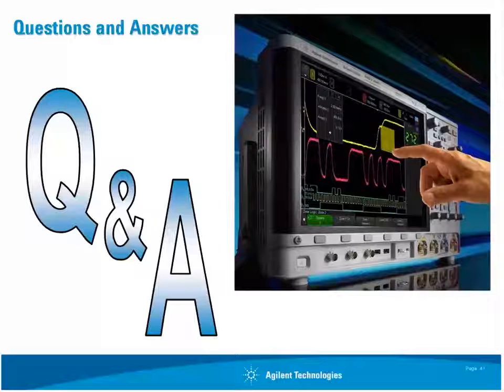What the fast waveform update rate is doing is actually capturing more noise. Noise, if it's random, if it's Gaussian, which is typical white noise, will have extremes that happen more infrequently. They'll have extremes of positive peak noise and negative peak noise that happen less frequently than the 1 sigma type noise.